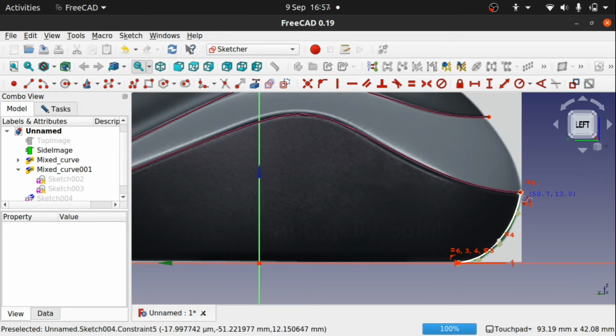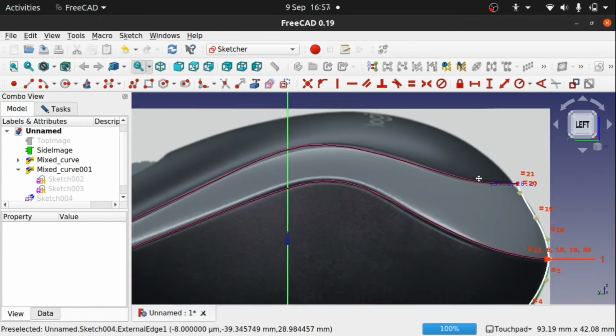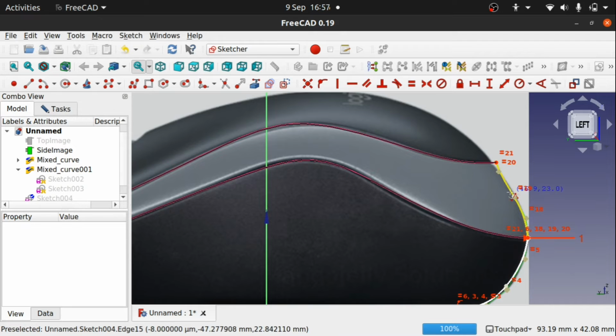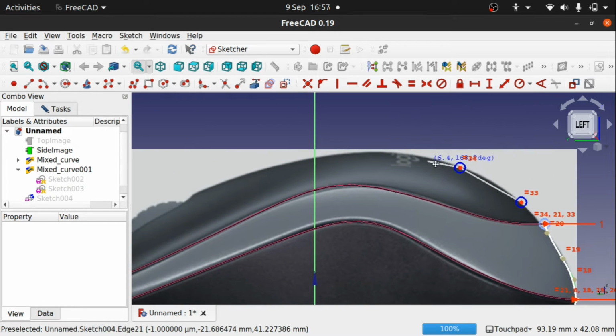This is important. And I'm going to reattach myself to there and sketch around, connecting up to the other B-spline, like so. Again, I'm going to hit escape, and I'm going to move this. So I've created 2 B-splines in here, inside one sketch. I'm going to create another one. So attach up to that line and move our way around here.